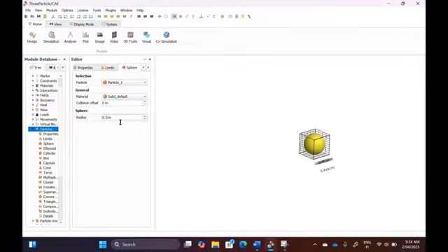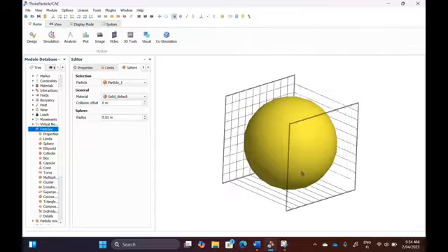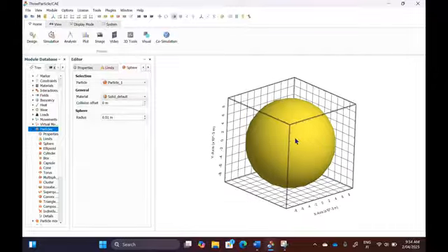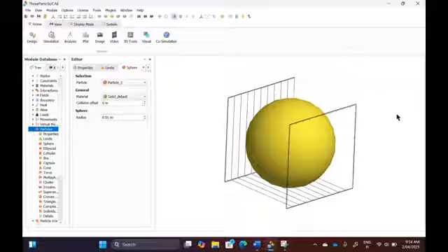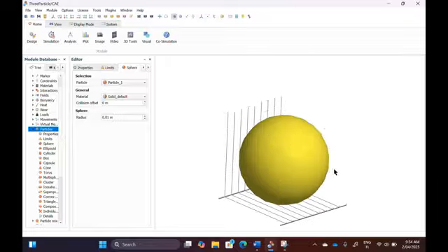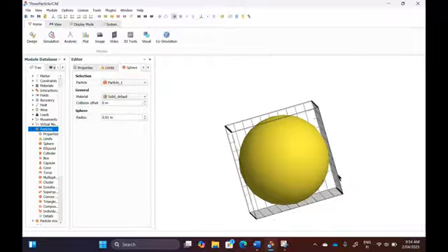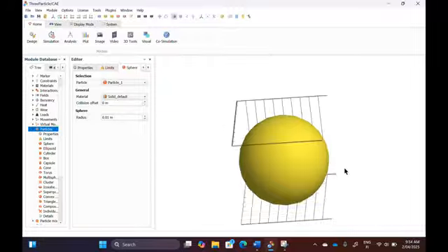You can see that here. Zoom in. If you double click your middle mouse button, so on your mouse wheel, it makes a zoom fit. It's the same as somewhere up here should also be the zoom fit. I guess that one. Yeah, zoom fit. Because if you are anywhere like that, you can just click zoom fit and it jumps to it. Yes. I think it's moving too fast.